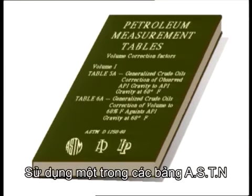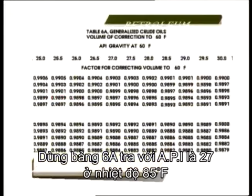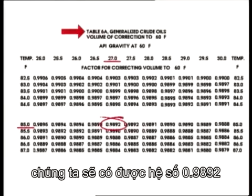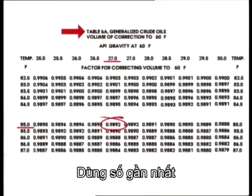Use volume 1 of the ASTM tables. Find table 6A. Against API 27 and a temperature of 85 degrees Fahrenheit, you find the factor 0.9892. Do not try to interpolate. Use the closest figure.